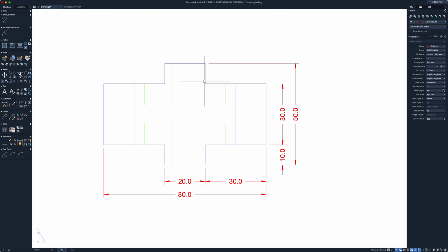Okay, so like I said, I could go through and dimension all these parts, but it's really going to just clutter the drawing with unnecessary dimensions. So we're going to, like I said, create a line of symmetry. Now we can use this one right here, which happens to be the center line for this hole, but that is also the axis of symmetry for the entire part. But it's also symmetrical this way. So I don't have a line of symmetry going across here, and we need those.